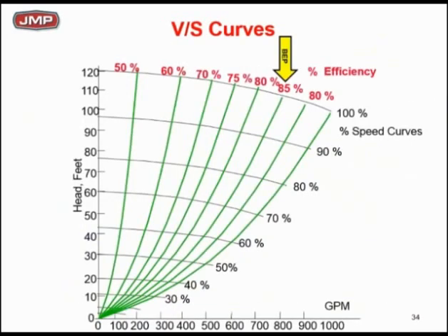Here we go back to my efficiency curves with a variable speed drive. Anybody's pump. This is what happens, and you kind of got to begin to pull these pieces together. And we're going to be repeating this a lot. So if you didn't get it the first time, maybe you'll get it again. I'm at BEP in this case at 85%. See my little yellow area at BEP at 85% efficiency. See my speed lines going from 0 speed to 100%.